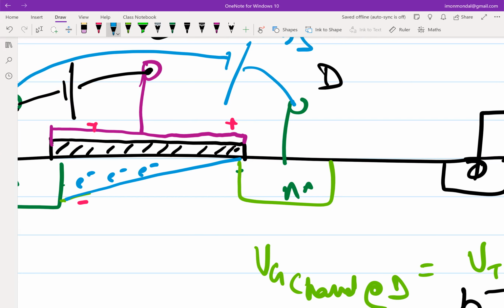The inversion charges actually go to the drain side, right? Yeah, that's true. So that's the dynamic phenomenon, right? As you keep on increasing, where does the charge go? But we are not talking about the dynamic phenomenon. We're talking about, you have increased the channel, you waited for some time, and you are trying to see what the charge profile is.